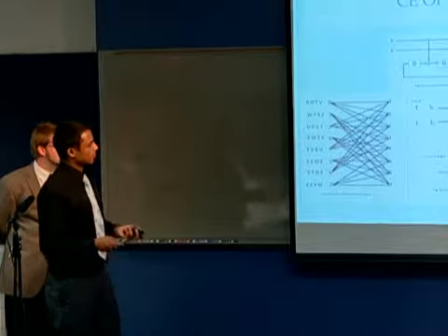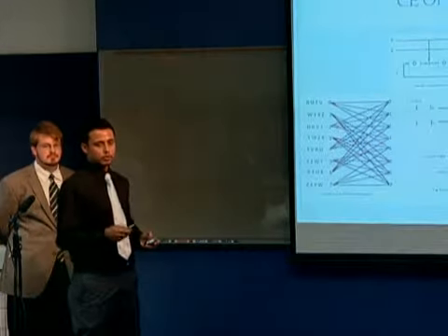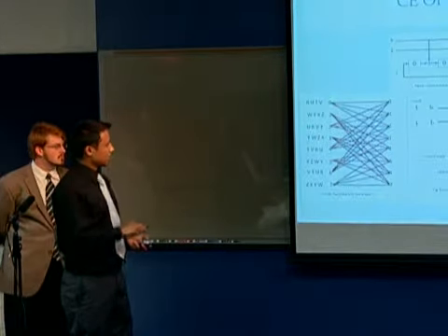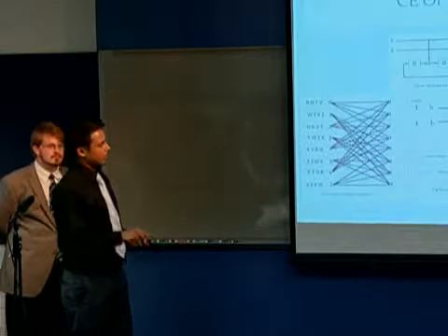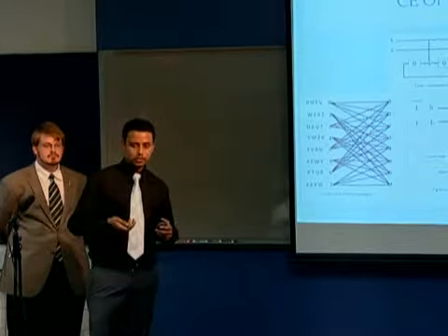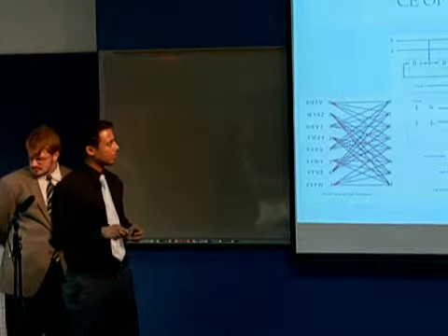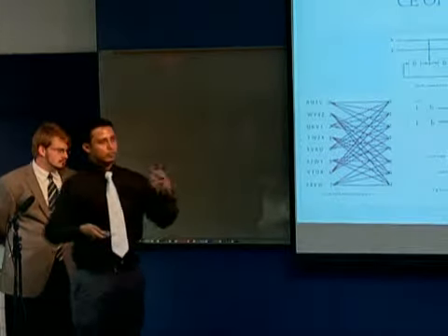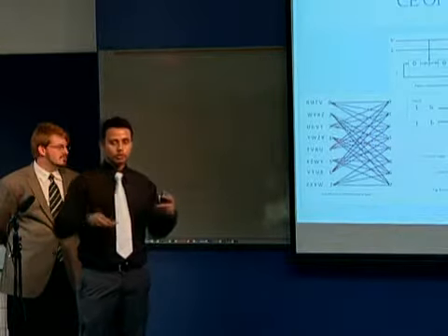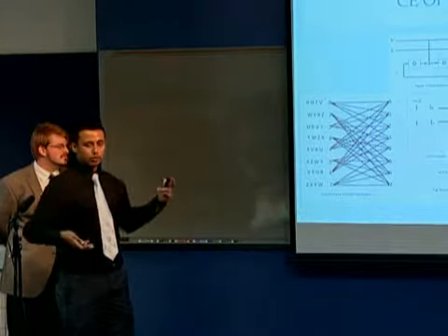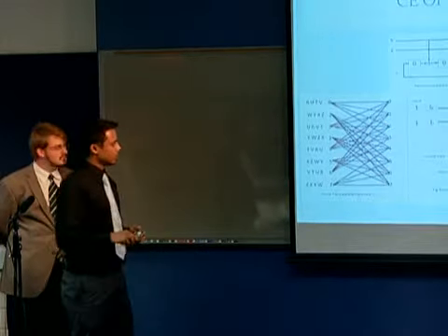And this is the convolution encoder of rate 2/3. Since there are 3 flip-flops, there are 8 states. And since there are 3 outputs, there are 8 different subsets. These subsets are again from Dr. B's dissertation, and each of these is 64 by 8, which means 64 points in each subset. So we have a total of 512 points, and each of these subsets has 64 points.